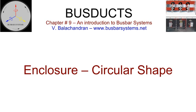The circular enclosure design is more compatible with a tubular conductor as any change in the direction in the run of the bus duct can be easily negotiated. It need not be restricted to a horizontal or vertical plane as in the case of a rectangular enclosure. Circular enclosure expansion joints are cheaper and easy to install.